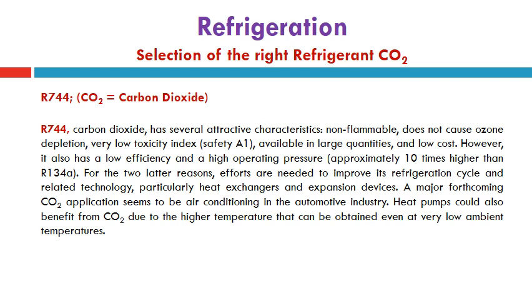For these two latter reasons, efforts are needed to improve its refrigeration cycle and related technology, particularly heat exchangers and expansion devices. A major forthcoming CO2 application seems to be air conditioning in the automotive industry. Heat pumps could also benefit from CO2 due to the higher temperature that can be obtained even at very low ambient temperatures, as can be seen in the problem solved at the end of the previous lecture number 6.